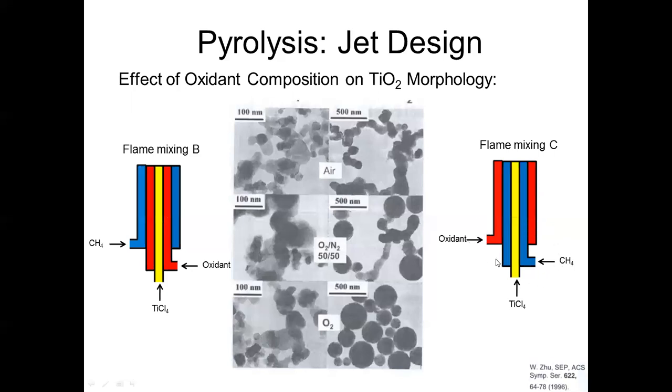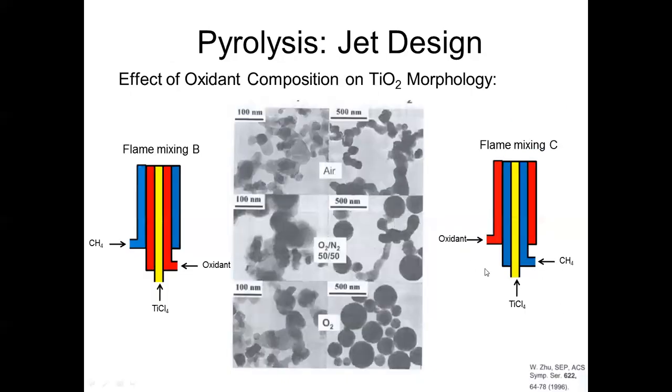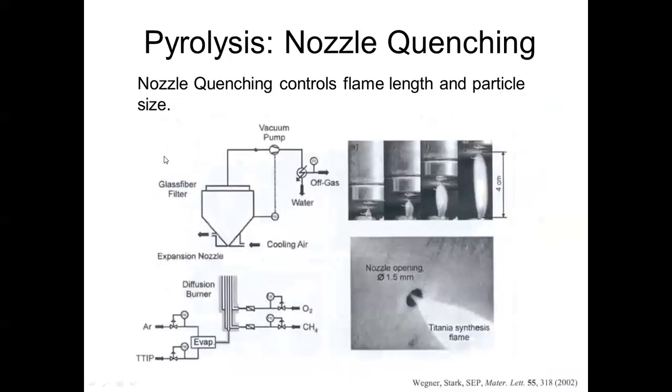So we have a couple things we're going to do at one time. We want to truncate the flame and then control the size of these particles through the burner design or the burner mixture. That's exactly what we do. We control the burner mixture down here, probably empirically. We're going to look at different configurations of mixing the gas together. And then what we do, which I thought was novel, is we typically have maybe a 4 centimeter, so two inches or so, of flame in here.